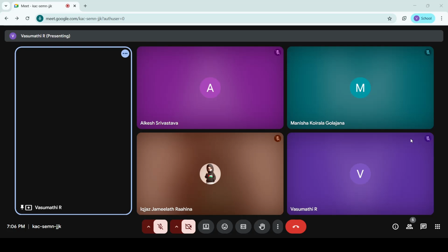You will be left with L by C divided by S square into RLC plus R plus S by CS. So this and this C will get cancelled. Then you will get SL by S square RLC plus R plus S into, so if we put VA here, V0 by VA, you will be left with SL plus S square RLC plus R. Right?